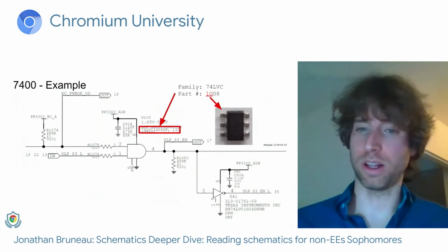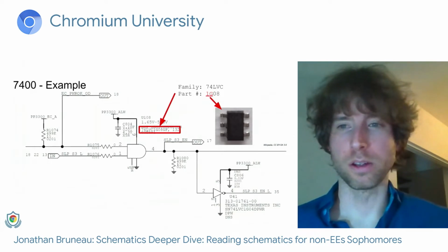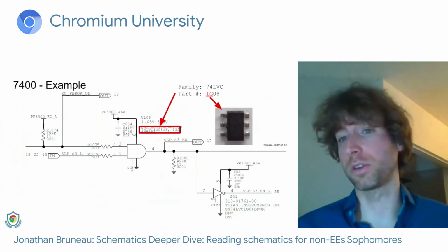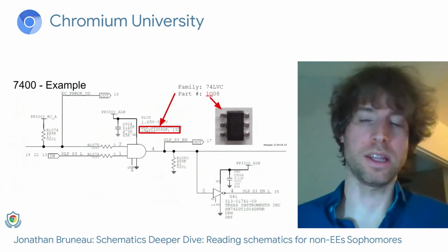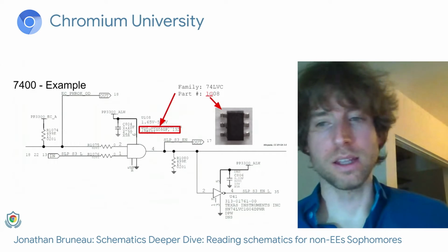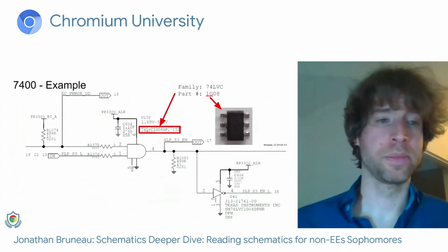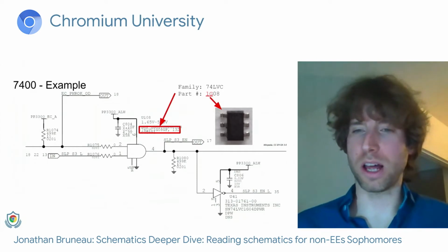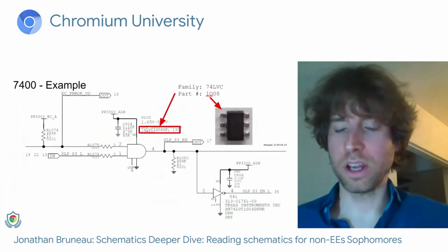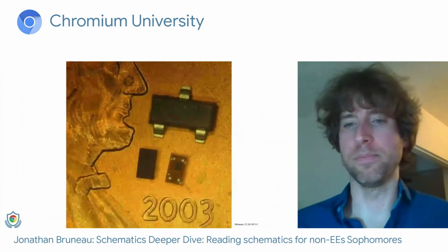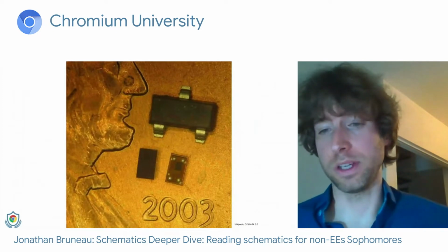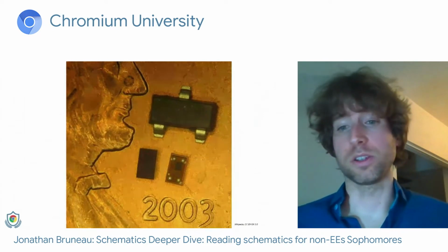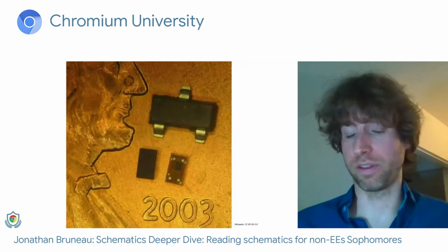And this is a small example with a 6-pin part. There's also sometimes a 2G version. So you might see 74LVC2G08, and that would tell you, okay, this is 2 AND gates. And this matters a lot, the 1 gate, because we can make them really small. And small means saving space, and saving space means saving cost, and also being able to put more stuff in the same area.